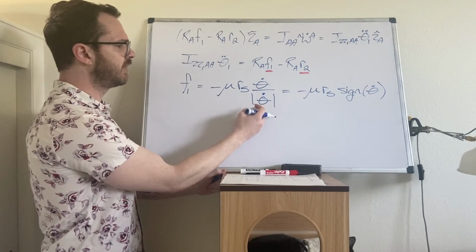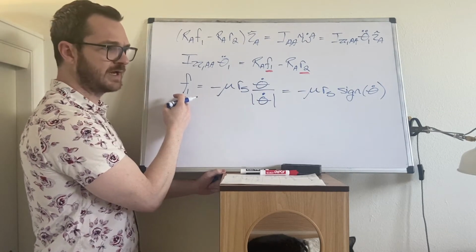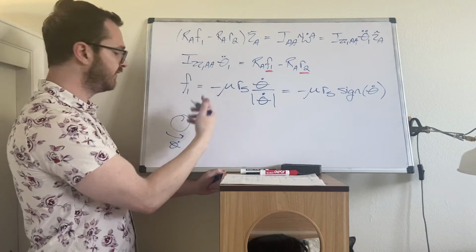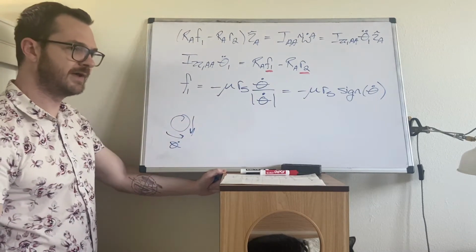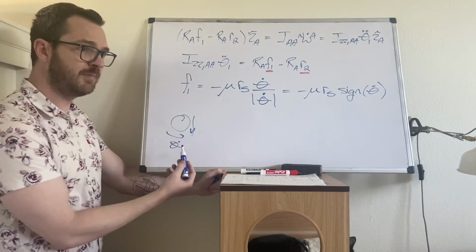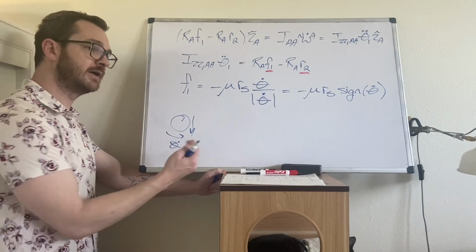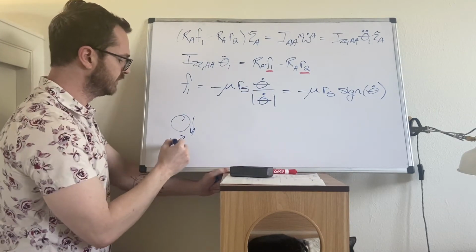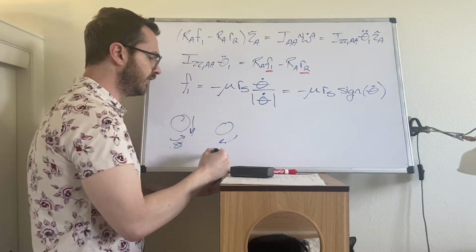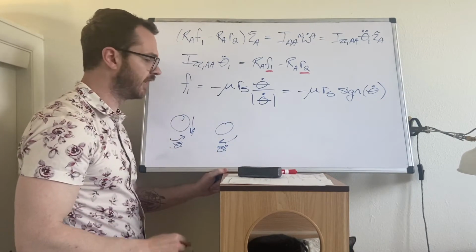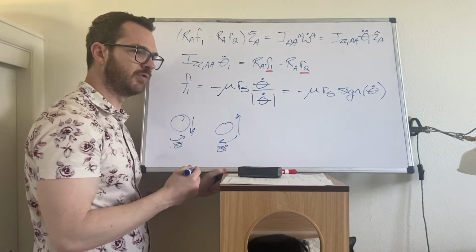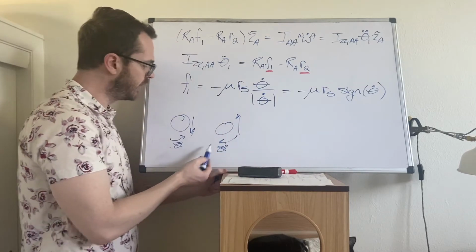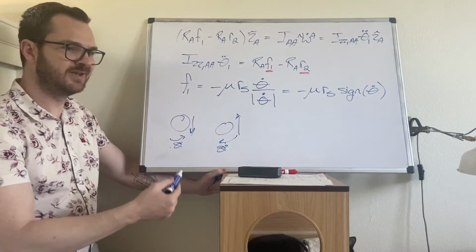If the disk rotates in a positive direction, then F1 is negative. Go back to the diagram. That means if theta 1 dot is positive, that means the friction points down, which makes sense. If the friction pointed up, that would actually contribute to the speed, and it would make it go faster. What happens if the direction reverses? Well, we'll just do a second one. Here we go. The direction has reversed. So here now is theta dot. Well, in this case, the friction is going to reverse. And now you have negative rotation and you have a positive moment created by the friction. So in both cases, the friction is going to cause the disk to slow down.